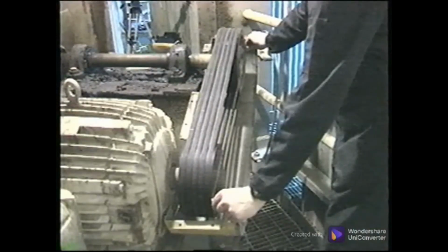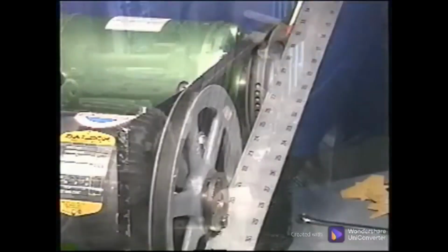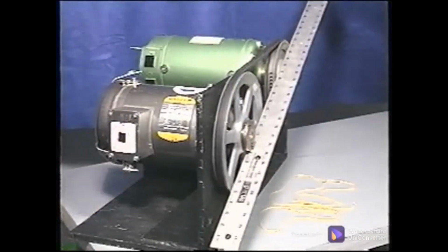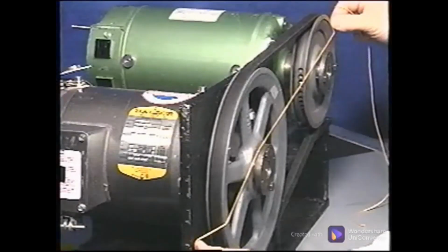They were misaligned about 1.5 inches. A straight edge can be used to check alignment, but a long straight edge just won't fit in a toolbox as easily as a 10-foot long string. And the string performs the job just as well when care is made to ensure that the string is not bent around a sheave edge.